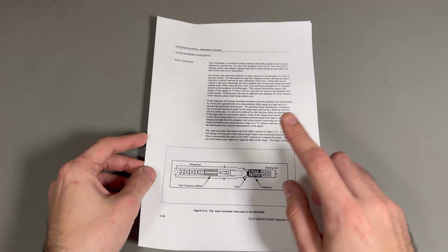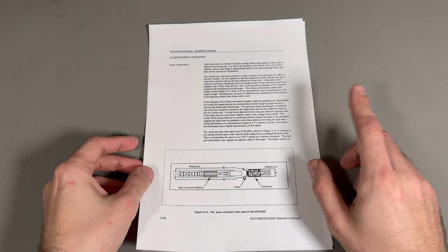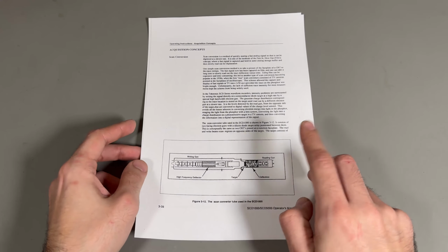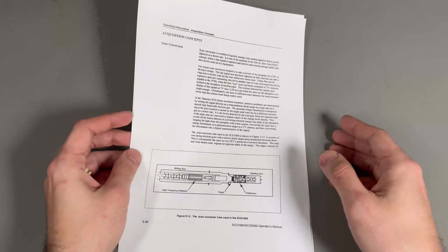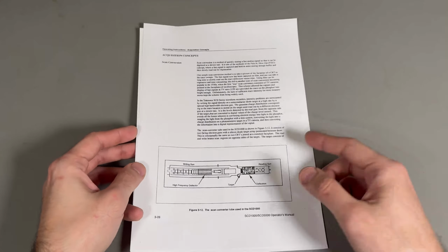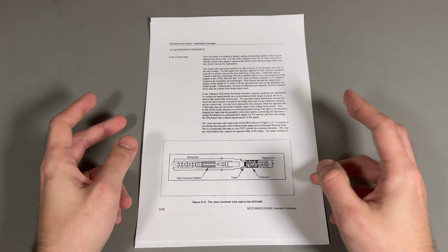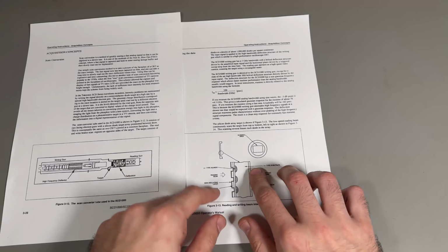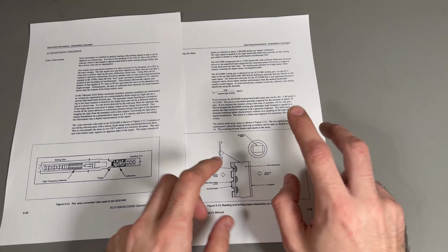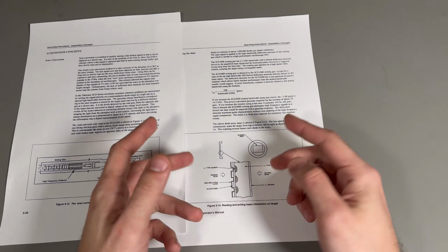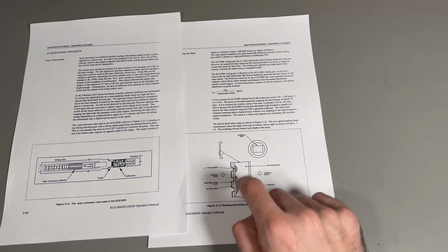A couple of interesting options were, and I'm going to show you some of them, because spoiler alert, I had two of these SCD5000s. One of them is a trigger, internal trigger, which lowers the bandwidth to a paltry 3.5 gigahertz from 5 gigahertz, because it has a delay line and trigger pickoff circuit and other stuff like that. And the other option is a fast centroider. So basically, in order to get a nicer looking signal, the computer inside has to interpolate, basically just an interpolation to reconstruct the original waveform from the data collected from the matrix here.